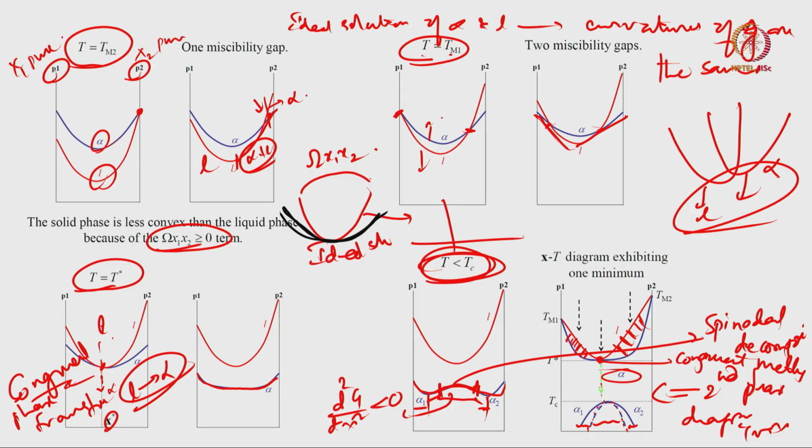So, this tells me that the alpha phase itself is unstable, but between this parabola or this line and this line, or this trajectory, this inverted U and this inverted U, right, the alpha phase is stable but metastable, right. So, it is still splitting up into alpha 1 and alpha 2, but it is a metastable state, right. So, this defines the miscibility gap, but this defines the spinodal decomposition. Okay.